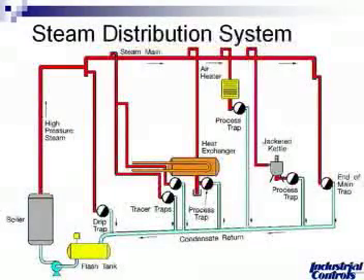This is a relatively simple slide, but what we're showing here is the basics of where a steam trap would be applied and how you would use it. You obviously have your boiler off on the left-hand side that will be distributing steam at a higher pressure. The reason you distribute the steam at a higher pressure is it's a very small specific volume, thus you can use smaller pipelines. The steam would be at the high pressure taken throughout the plant.